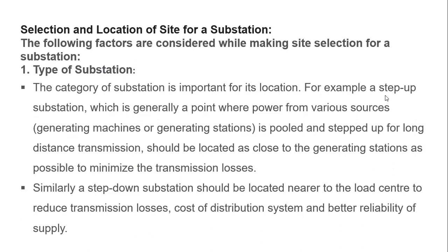Okay, for example, a step-up substation, which is generally a point where the power from the various sources, that is generating stations, is pooled and stepped up for long distance transmission, should be located as close to the generating stations as possible to minimize the transmission losses.